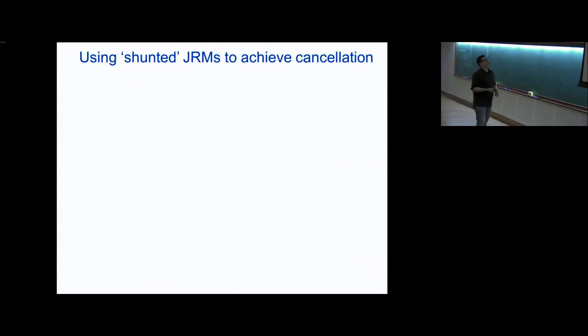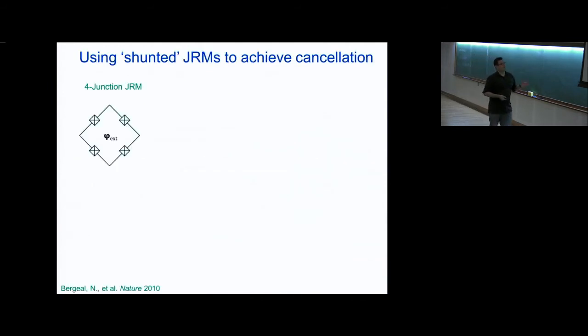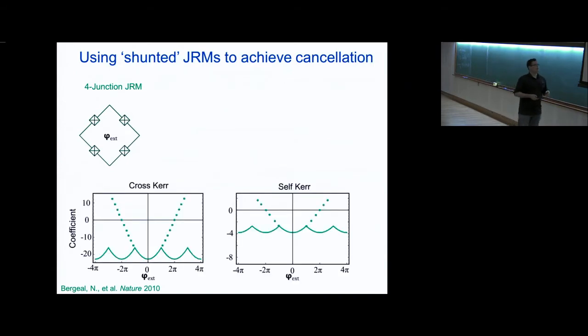Okay, so we looked now at several different variations on this ring that powers the Josephson junction, powers the amplifier. So the canonical simplest ring is just no shunts at all. But when we look very carefully at the cross-Kerr and self-Kerr coefficients, we realize that the problem is that we are trying to go to a point of pure third-order nonlinearity and no fourth.